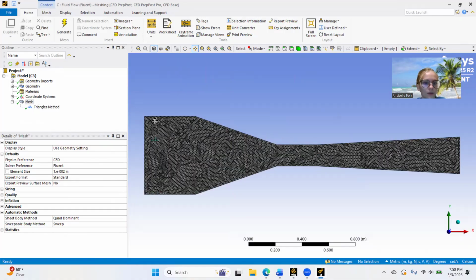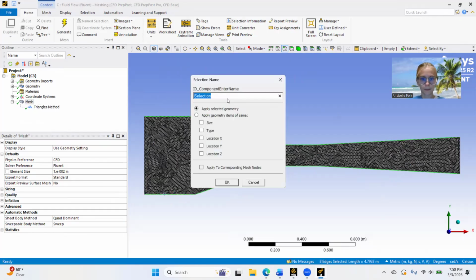And here as well, we're going to name, grab that edge piece. We're going to name our walls. Hold down Control and just click our bottom and top exterior walls, not our side walls. Click in, and then we're going to set this as wind tunnel walls.